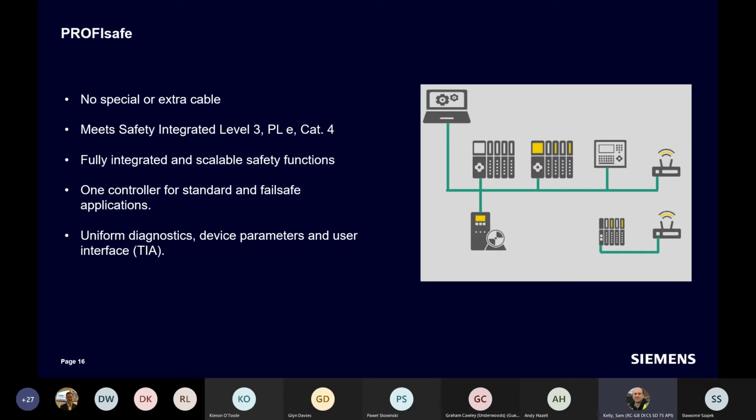So by doing our safety over the Profinet network, everything's fully integrated in the one engineering tool, TIA Portal. We also get our diagnostics information through the network, like we've already seen. So, for example, when I did the breaking of one of the wires, we got the discrepancy fault come through. Standard system text that I haven't had to write, it's just system generated.